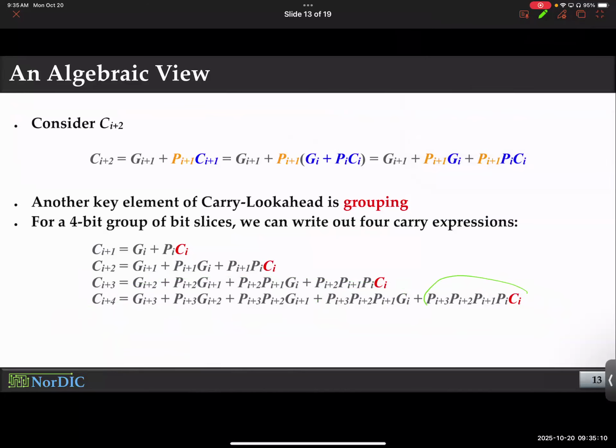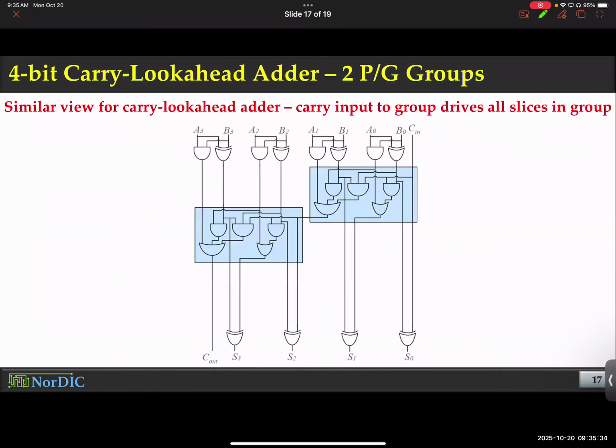As we just said, for this particular term, it has 1, 2, 3, 4, 5 inputs. So it needs a 5-input AND gate, and then a 4-input AND gate, and then a 3-input AND gate, a 2-input AND gate, and then a 5-input OR gate. If you do a 2-stage implementation and break it down into multiple stages, it will take even more, maybe, right?